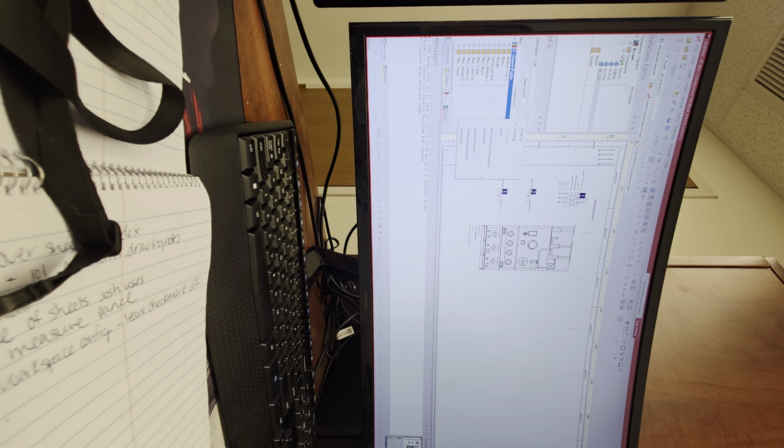Looks like it's missing the actual symbol name feature as well. Right click, search configuration. And this will be your symbol name that I was trying to think of. Symbol name. And edit to the right. And then change the order of these two by using the second list of buttons on the right side, that shows up and down. Okay, that looks proper. Symbol name comes first. Click OK.